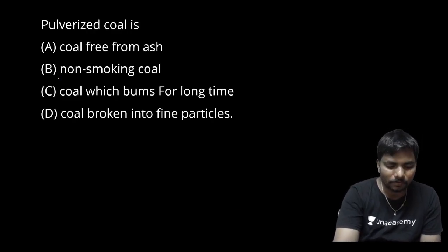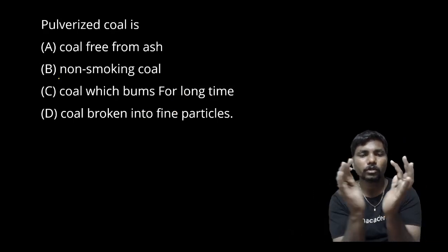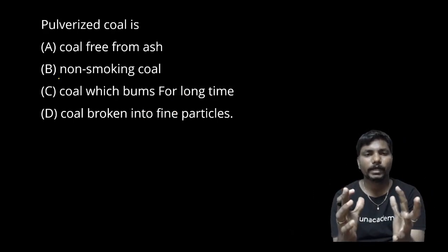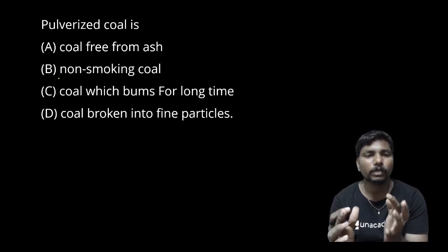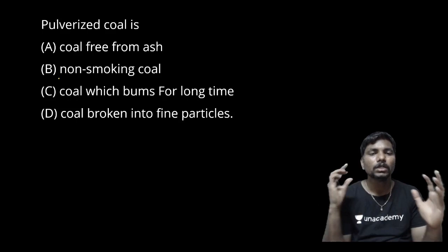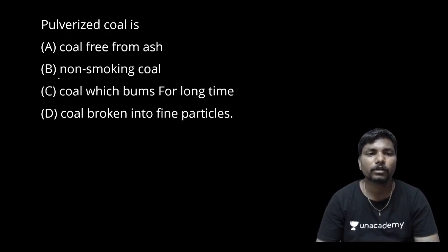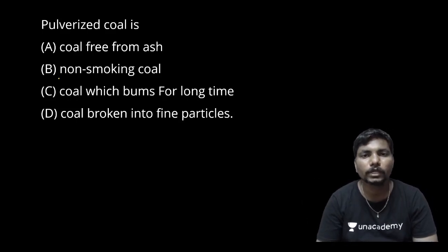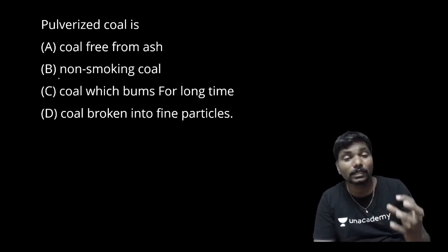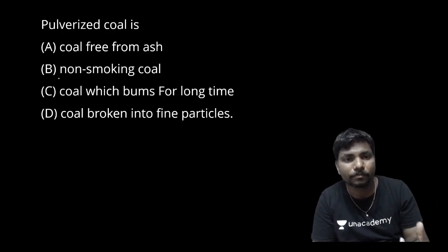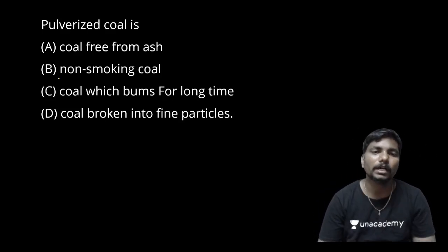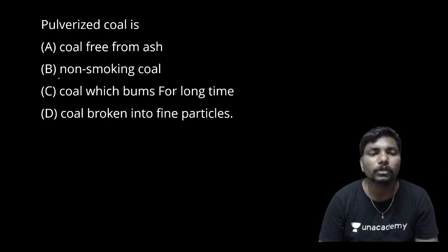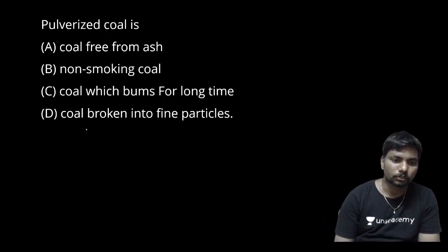Pulverized coal means, we have the coal in solid form, so we have to get powder form from that. Why? Because we are not using anthracite type of coal, generally bituminous type. To get the calorific value, the high amount of heat, within less time, we have to convert that solid coal into powder form. That process is considered as pulverization of coal.